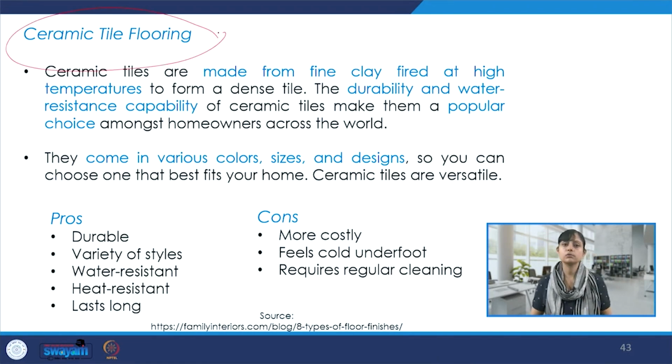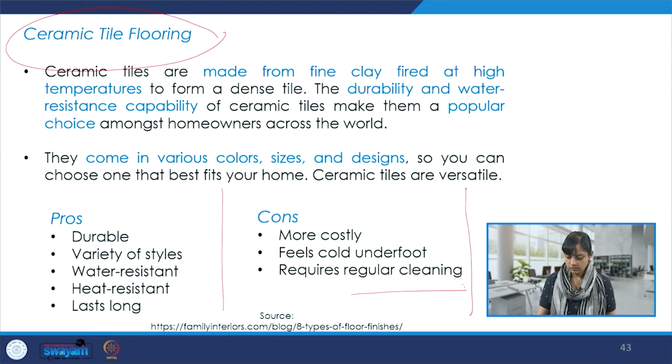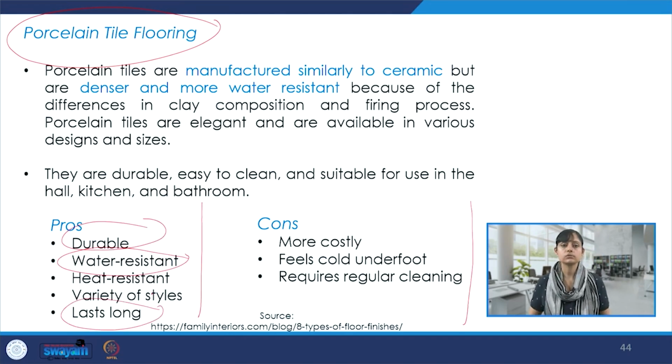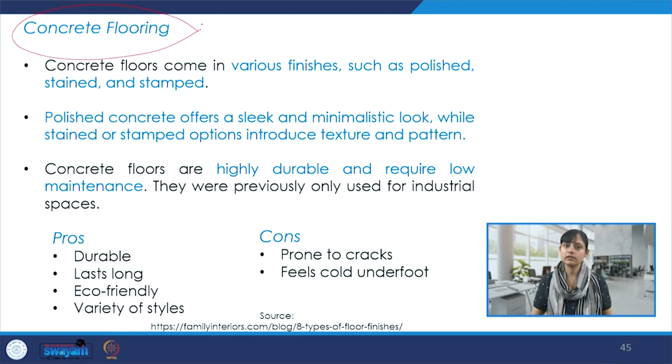Ceramic tile flooring, of course, made from fine clay fired at high temperature, comes in varied colors, durability, water resistance, so all the advantages and disadvantages. It requires regular cleaning, and it may appear cold to your feet. Then there is porcelain tile flooring, and these tiles are manufactured similar to ceramic, and they also have advantages and disadvantages, but they are very water resistant, durable, and they last quite long, so they can be used for flooring. There is concrete flooring again, which is still used in lots of cases, and they could be polished, stained, stamped, and they could have different kinds of textures and patterns on them. And they require very, very low maintenance,